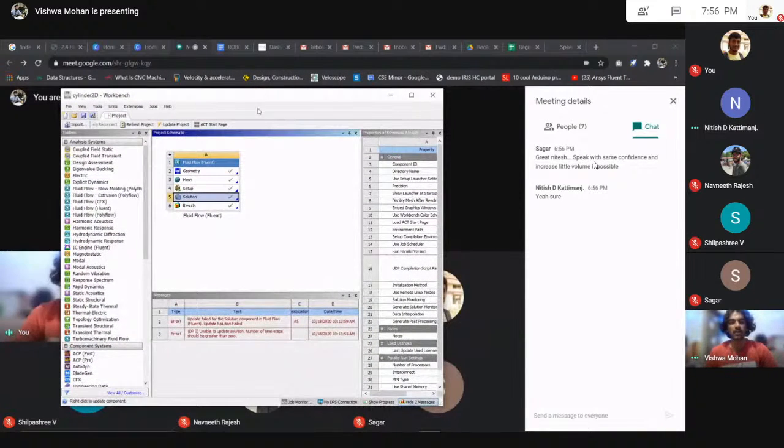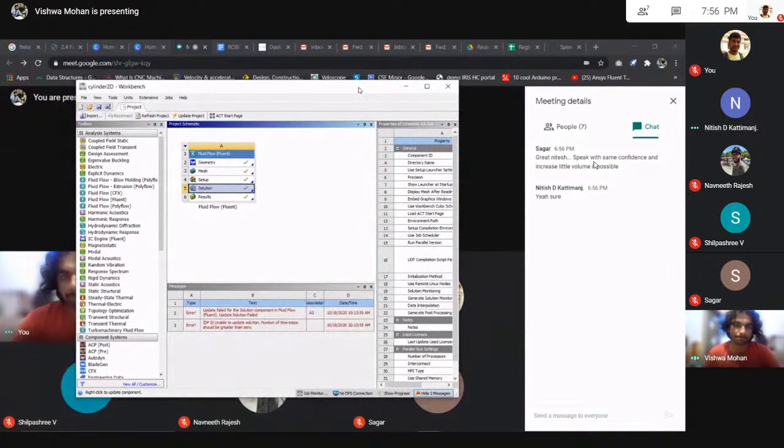All right, cool. So guys, this is how Ansys Workbench looks. The way I talked about it, CFD involves the CAD model, which is given in the geometry. It involves meshing, which is discretizing. It involves setting up boundary conditions, solvers, and models, which goes in setup, and then the solution part. It solves, and then you get post-processing through results.